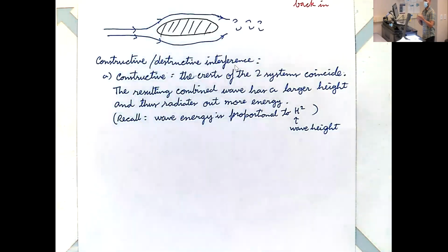If you go faster, what happens to your drag? Instead of it being perfect, it's going to kind of get on top of that bow. It's going to start planing, right? Your bow will rise out and your stern will dip. Will your drag increase or decrease? It depends on the shape of the hull. If you have a cargo ship that starts planing, hopefully that never happens. That design is terrible for planing. So hulls that are designed specifically for planing will reduce wave drag.